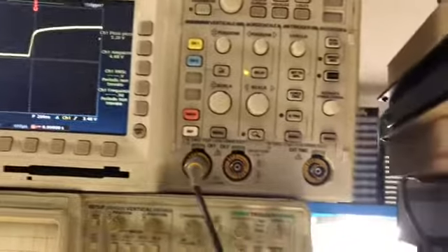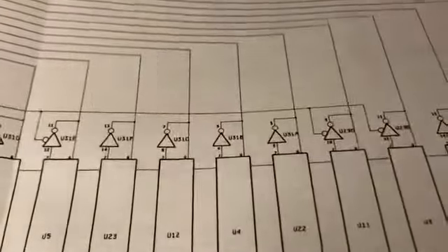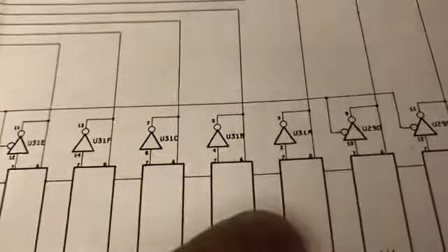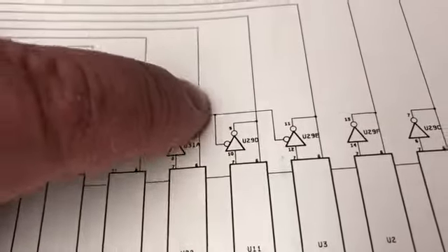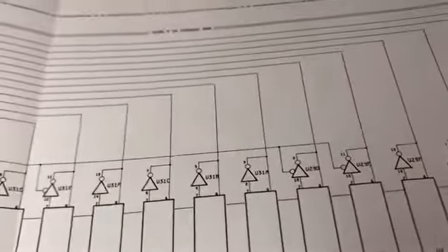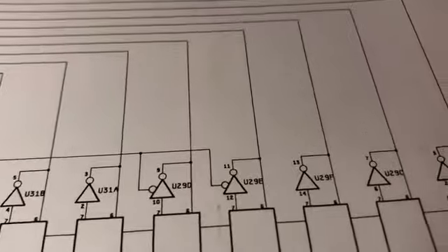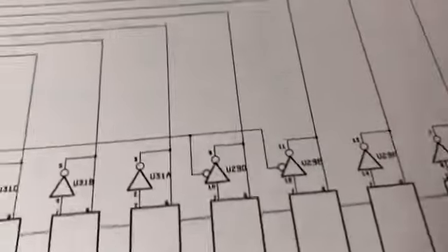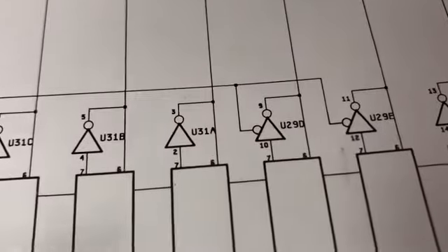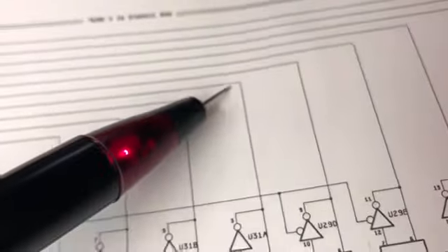So perhaps the IC that I have already checked just a few minutes ago. So U31 is loading the output of the RAM. So when it is enabled, it does not give us the signal that we should have. And this is, let me follow it. Let me do it together with you. So it is over there, over there.